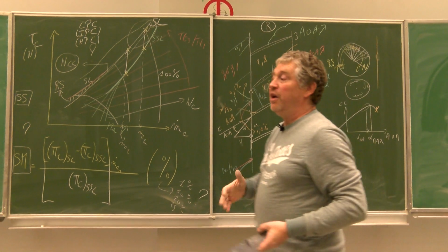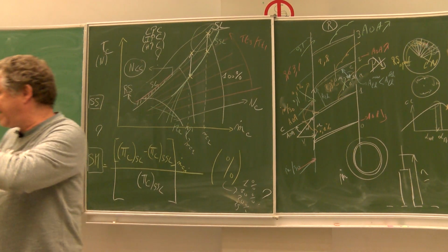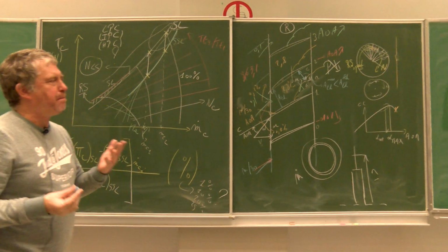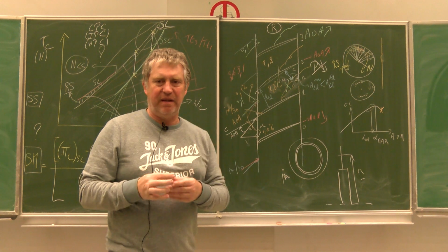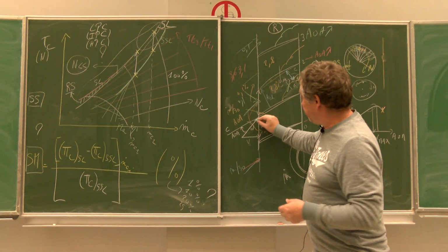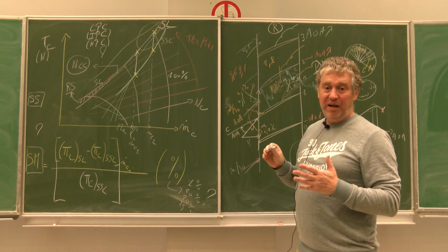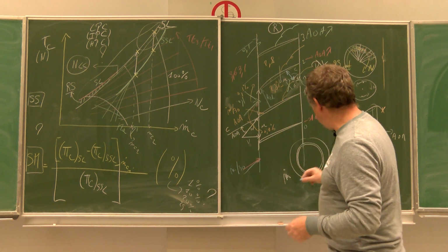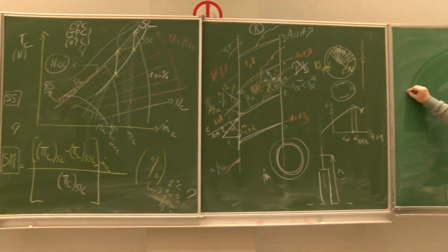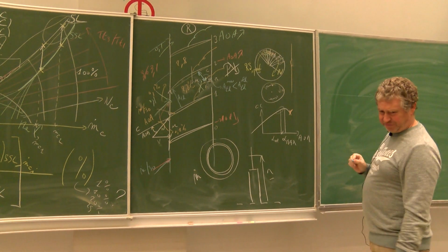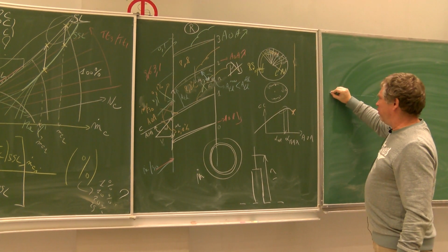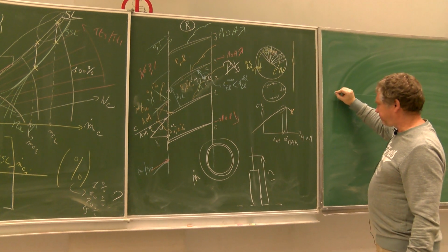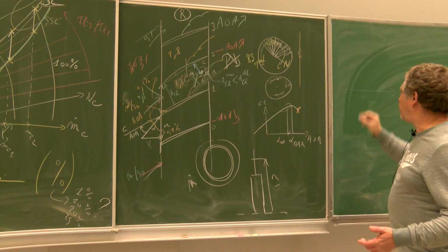And so many times per second, with a frequency that is depending on the rotational speed, you will have the velocity triangle on the blade that will be changed. And what will you see if you take the loads? On the blade, normally you have something that is, let's say, a constant load.